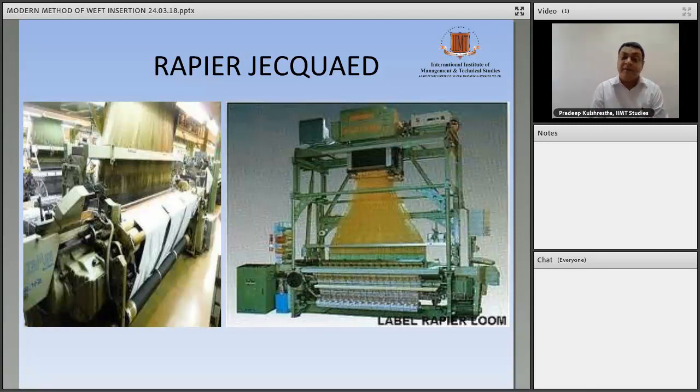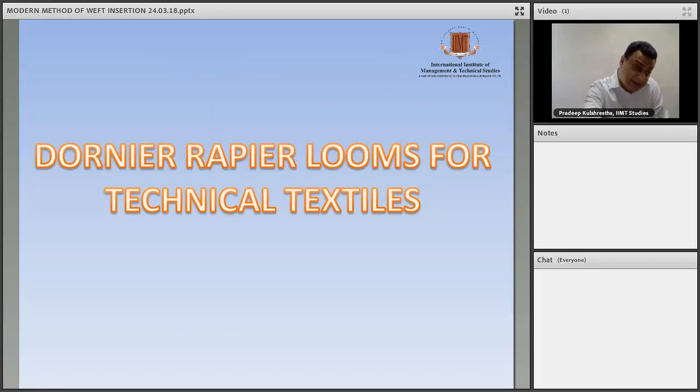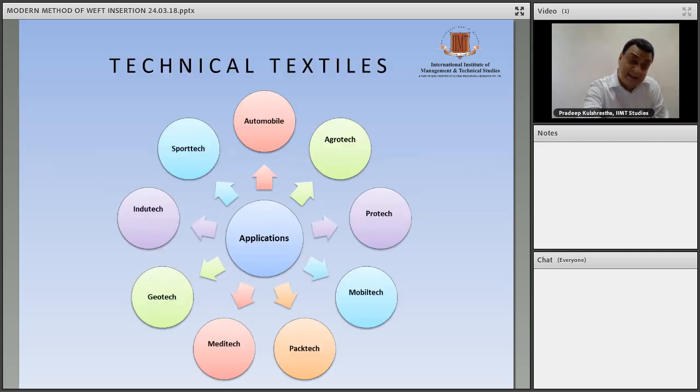Now we have the provision of the tappet for plain fabrics, then dobby for designs. Many dobbies are coming: Staubli dobbies, KR2, KR1, KT dobby, then Promatech. Then jacquard. Jacquard is mostly used for more elevated figures on the fabric. These are the jacquard heads mounted on the top of the machine. They are single cylinder, single lift jacquard, or double cylinder, double lift jacquard, like this. These are the mechanisms of the jacquard, making very elaborate figures and designs of the fabric.